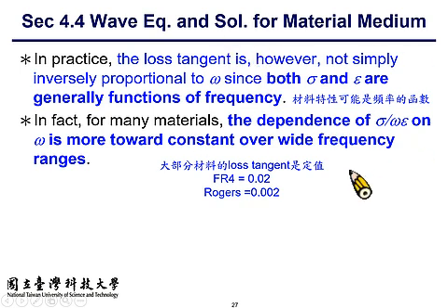So most likely we can still say that the loss tangent or the permittivity are constant for a particular band, say microwave, millimeter wave, terahertz, or infrared. In individual frequency bands, they can be constant, and the number can be somewhat different in the optical band and the millimeter wave band. If the band frequency difference is very large, then the number can be different.